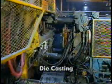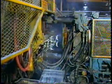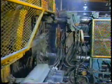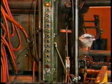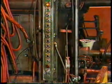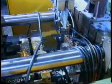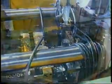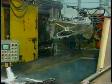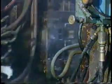Die casting is a rapid, high-production process for simple or complex, often thin-wall, precision parts. Castings are usually small to moderate in size and cast of non-ferrous metals. The molten metal is forced under high pressure into the die of a horizontal, sometimes vertical, die casting machine. One die half is attached to a fixed platen, the other die half to a movable platen. Die casting can produce a single part or multiple parts in a single metal charge, also called a shot.